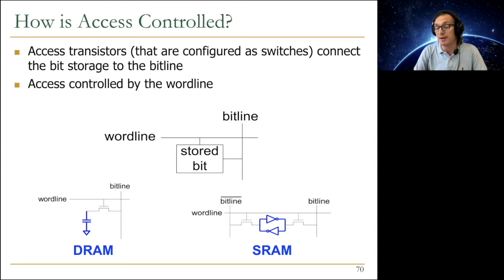But if you have smaller memories, it's not going to be as energy intensive, right? That's what the numbers showed, actually. If you have smaller SRAM, the energy costs are much lower. Also, there may be other trade-offs, but I'm not going to get into them right now. If you're using lookup tables to do computation, it eliminates data movement to do computation on a processor or an accelerator, then it may actually be a net gain. Okay, very good questions, though.